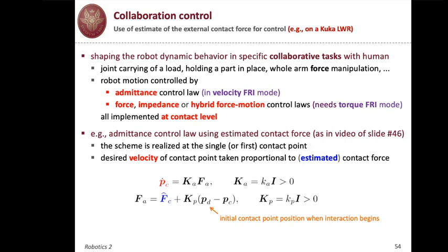And from this FA, which is built by a proportional controller plus the estimation of the contact force, through a gain, you generate a velocity at the contact point. Pay attention. And then this needs to be realized by joint velocities at previous joints. Okay? So this is one possible scheme. Of course, dynamic schemes are much more involved. We will see one of them later on, but just in a sketchy way. But they are based on feedback linearization, essentially.